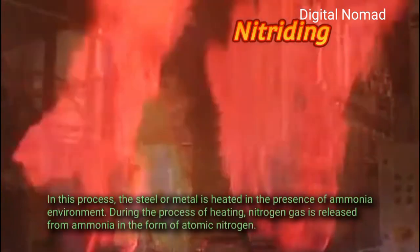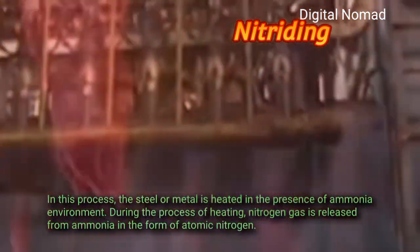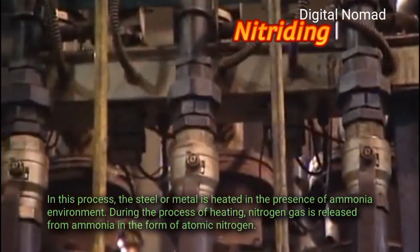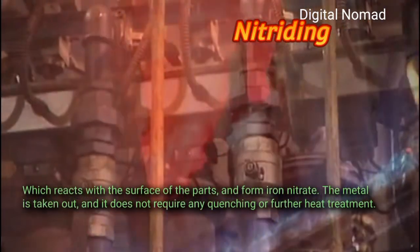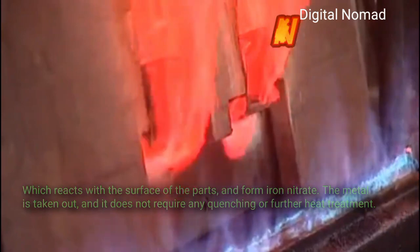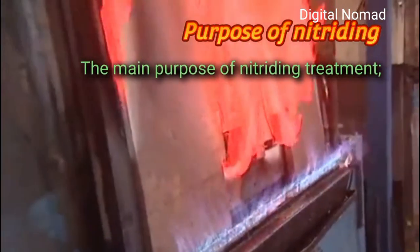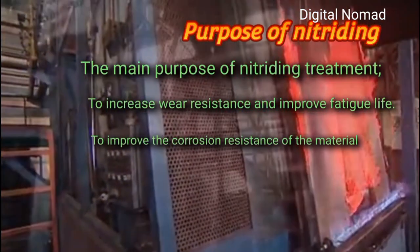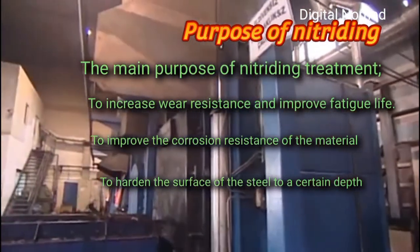In this process, the steel or metal is heated in the presence of an ammonia environment. During the process of heating, nitrogen gas is released from ammonia in the form of atomic nitrogen, which reacts with the surface of the parts and forms iron nitride. The metal is taken out, and it does not require any quenching or further heat treatment. Purpose of nitriding: to increase wear resistance and improve fatigue life, to improve the corrosion resistance of the material, to harden the surface of the steel to a certain depth.